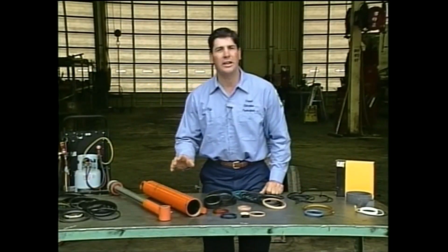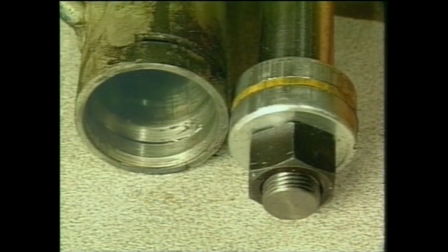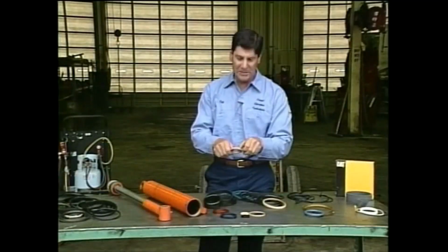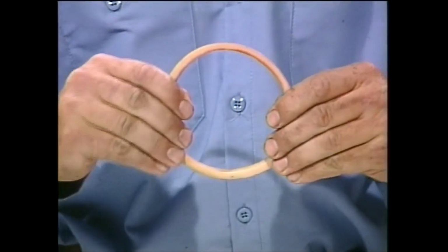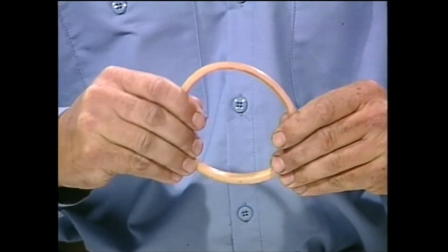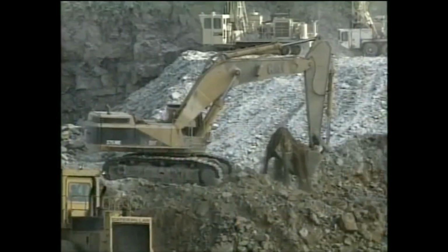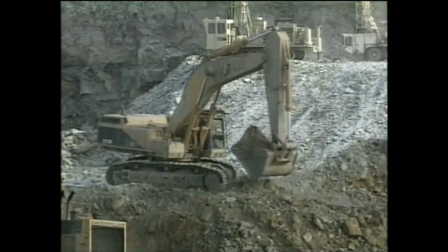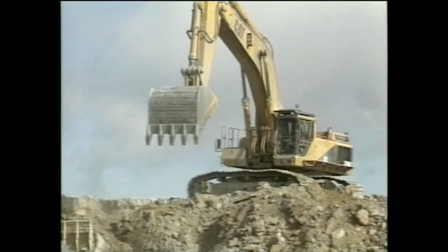Abrasion scratches clearly indicate a lack of maintenance. Dirt and wear metals easily damage cylinder walls and piston seals. Piston seals harden with age and heat. Seals that have hardened from heat are not elastic and will not seal against hydraulic oil pressure. Additionally, as they harden, they also easily crack. Cracked seals provide a leaking surface for high-pressure oil, thus reducing the cylinder's power and response time.